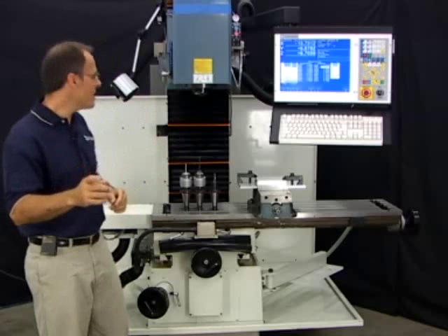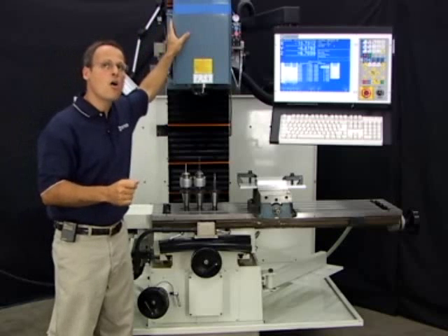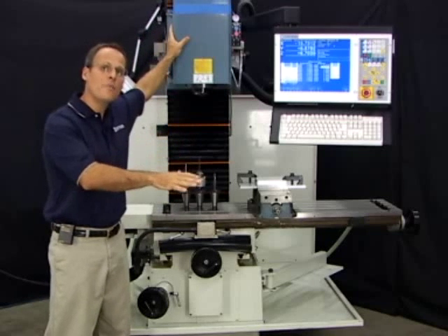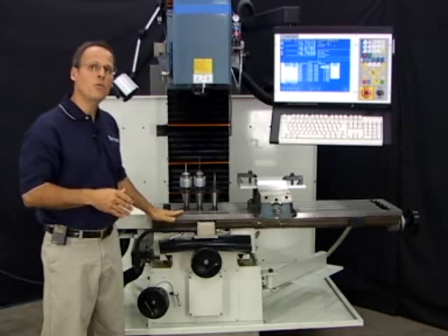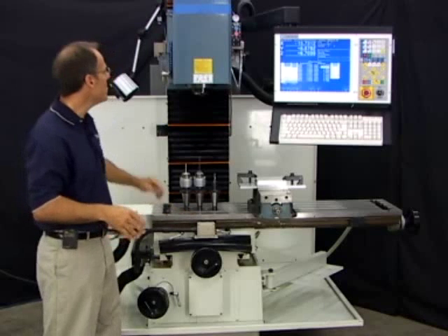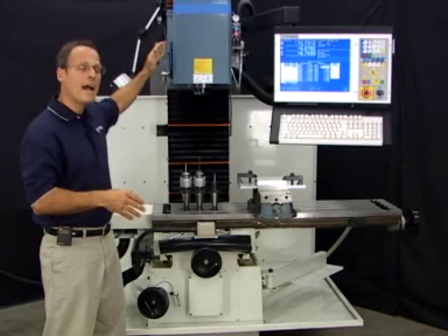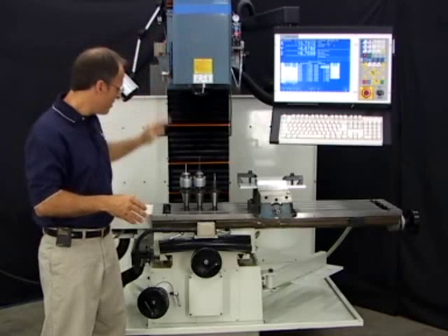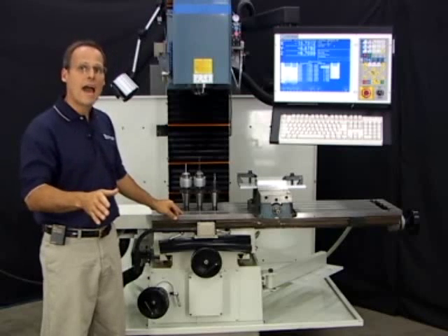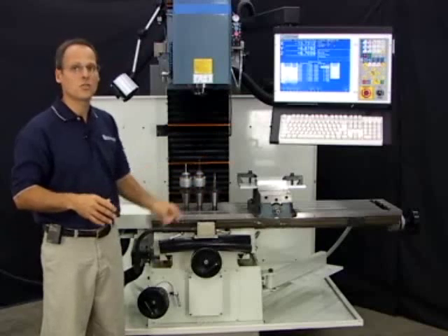I'm going to show you right now the most common method when using a bed mill or a machining center. Because there's a unique thing about a bed mill or a machining center: the distance from Z home, which is where we're at right now, which is where the head's going to be when you're done homing out, to the top of the table is always the same. The table doesn't move. The only thing that moves here in the Z is the column. So when the machine's done homing out, that distance from this point to the top of the table is a fixed distance. We're going to use that fact to come up with a height offset value for each individual tool.